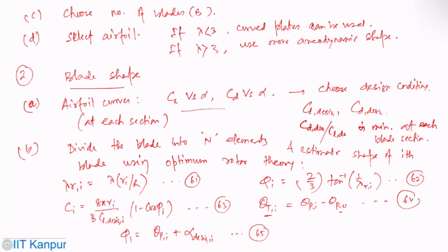Now, using this optimum blade shape as an initial guide, we can select a blade shape that promises to be a good approximation. And also for ease of fabrication, some linear variation of the chord, thickness, and twist might be chosen.